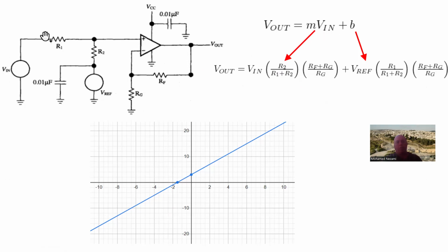So to solve this case, Vout is equal to Vn multiplied by, first of all, the gain that comes from these two resistors, which is Rf plus Rg over Rg, the same as 1 plus Rf over Rg. Plus, this voltage gets split at this node, so we have a voltage divider between R1 and R2. So this is the AC gain. Now the DC gain, the gain for this one, is basically the same thing: this ratio, which is 1 plus that, and then a voltage divider that divides this DC between these two resistors right at this point, okay?